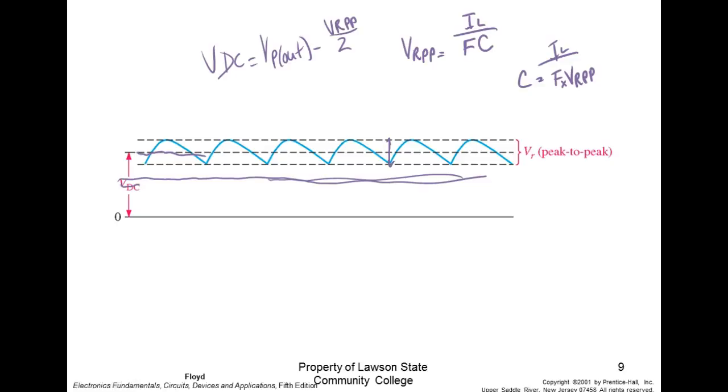So when we get a regulator, our unregulated voltage has got to be more than what we're trying to regulate at. And then what we do is we regulate. So if this was a 5-volt regulator, it's going to be looking at that, which is really nice, good DC, right? Does that make sense? But what are we going to have? We might have to have at least 7 volts unregulated down here for our regulators to work.